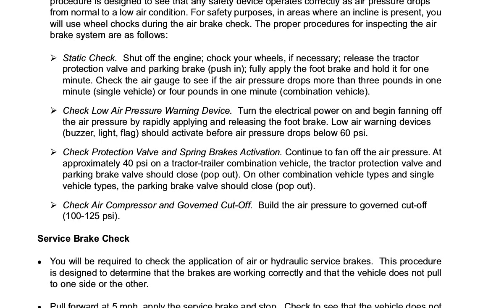Check low air pressure warning device. Turn the electrical power on and begin fanning off the air pressure by rapidly applying and releasing the foot brake. Low air warning devices, buzzer, light, flag, should activate before air pressure drops below 60 psi, pounds per square inch.